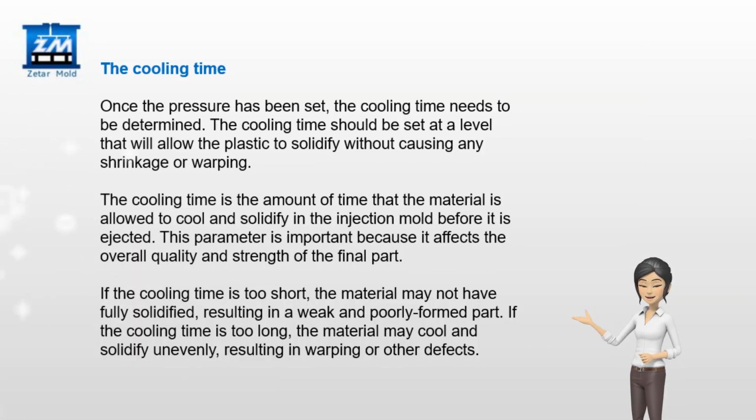The cooling time. Once the pressure has been set, the cooling time needs to be determined. The cooling time should be set at a level that will allow the plastic to solidify without causing any shrinkage or warping. The cooling time is the amount of time that the material is allowed to cool and solidify in the injection mold before it is ejected.